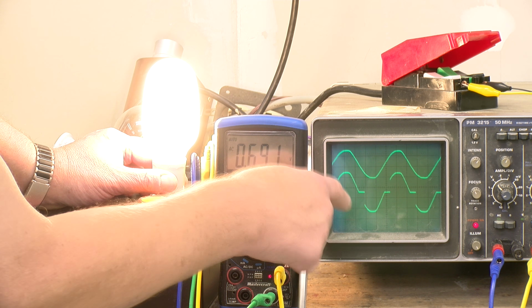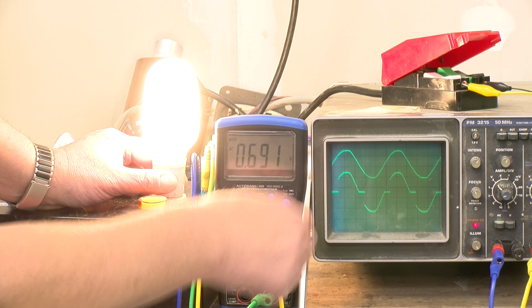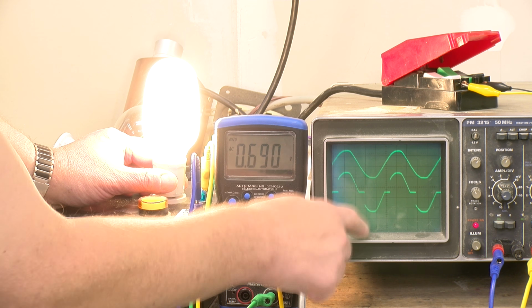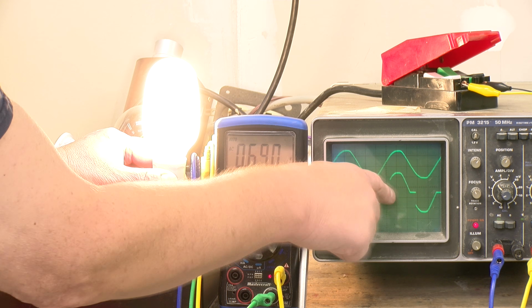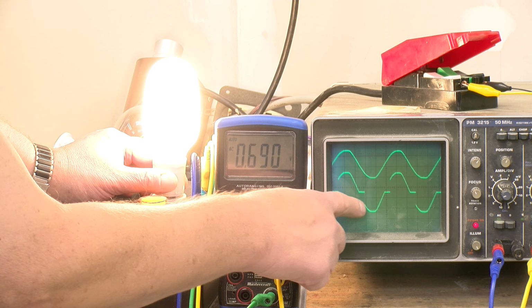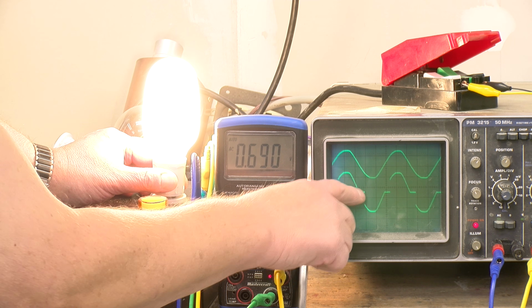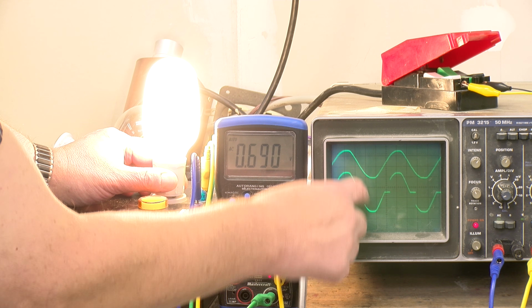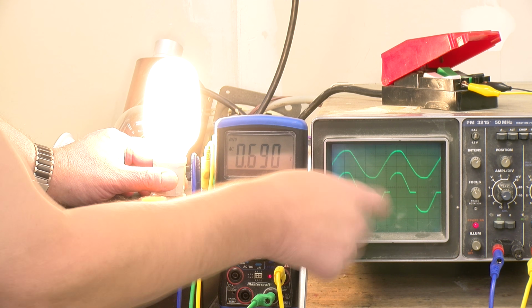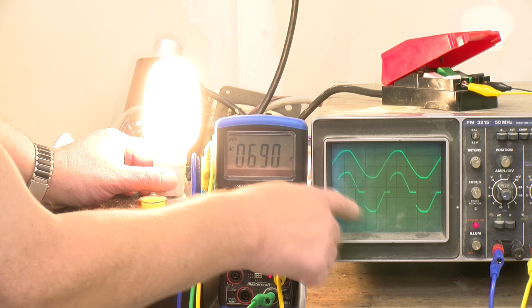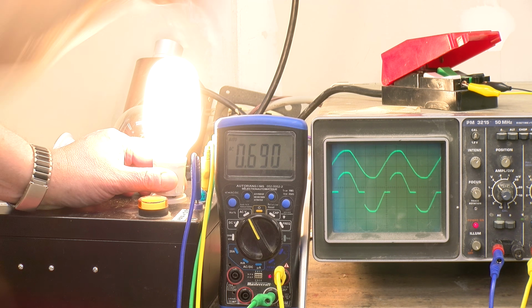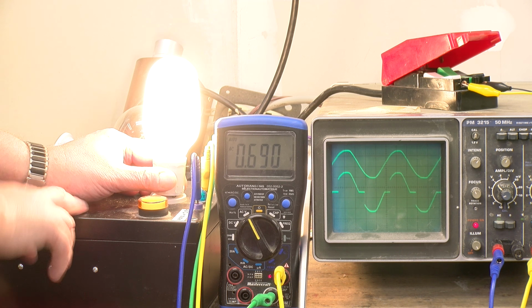There would be a triac inside the bulb with some sort of a timer circuit, and the more it delays the current being turned on, the dimmer the bulb will get. So over time we would see the delay of the bulb turning on to progress more and more through that cycle. So there would be some harmonics, high frequency components in there because of this, but it certainly wouldn't be nearly as bad as many of the other things we looked at.